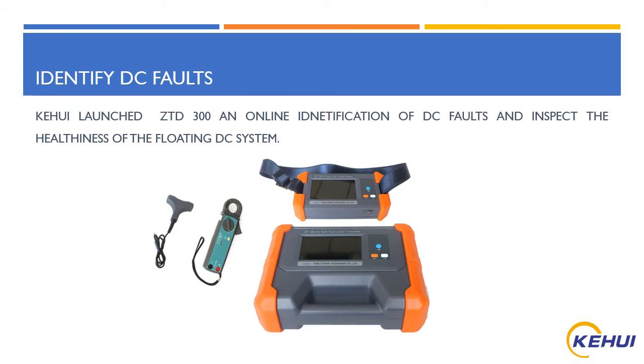The conventional method is to switch off and switch on each feeder to see whether the system is getting stabilized or not, which also helps to identify which feeder is faulty. In that case, if a wrong feeder is switched off, it can create a lot of damage to the asset or other electrical failures in the system. To avoid such cases, we have launched a new online DC earth fault identification system.